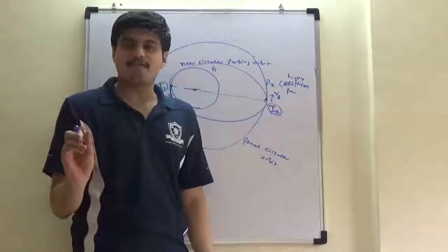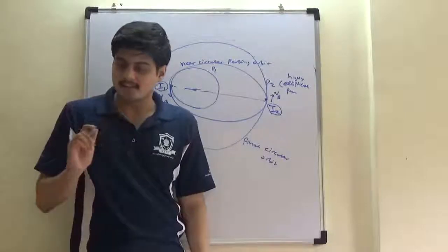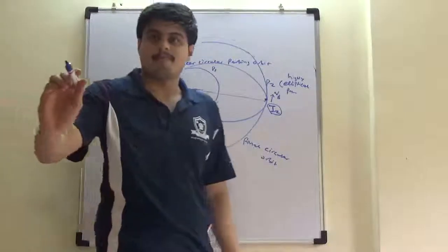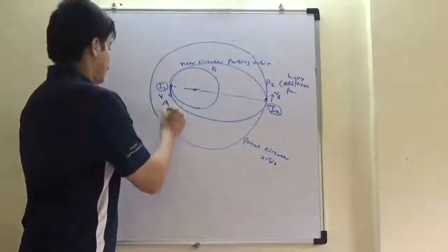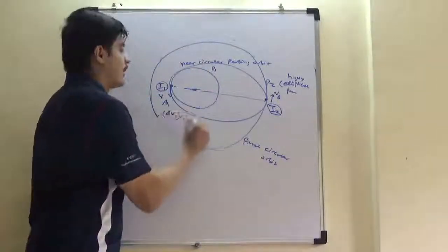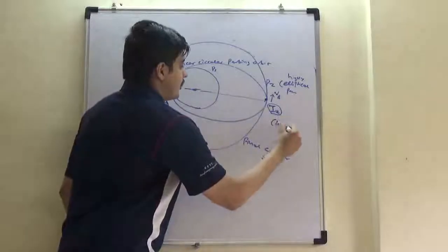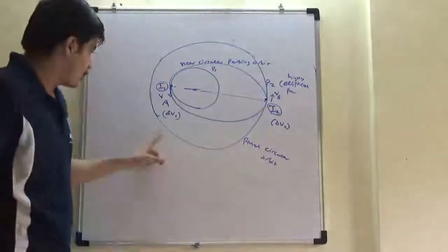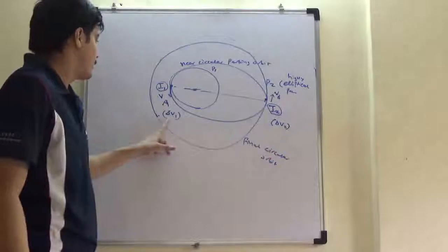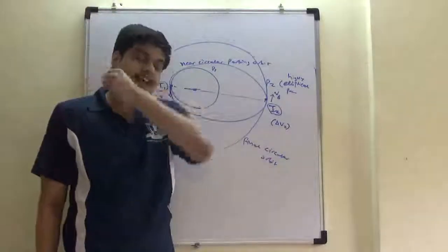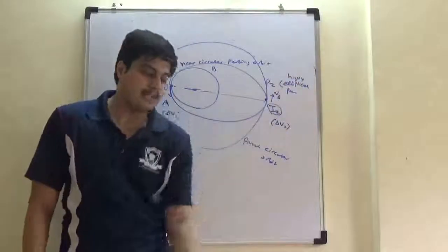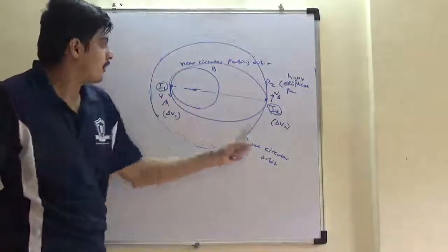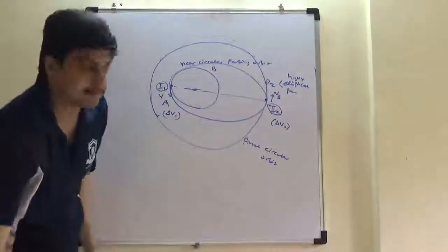You instantaneously fire your engines for a few seconds so that it goes up. There is hardly any drag in space, right? To 4. So here you get delta V1 and here delta V2. Your objective is to find these delta Vs so that you can find out how much time I should keep my ignition on, and therefore how much fuel to carry from the ground for inter-orbit transfer.